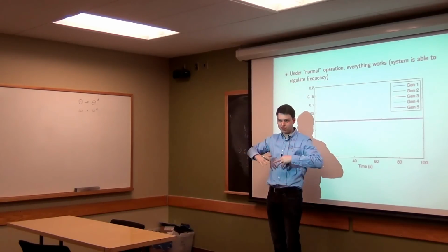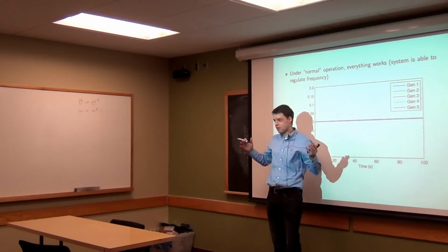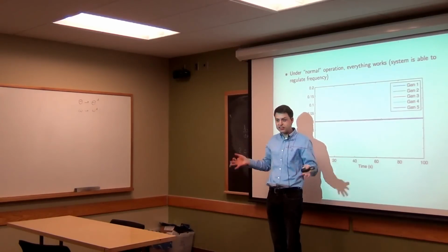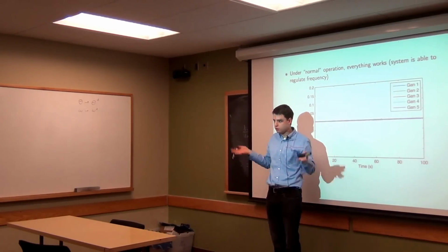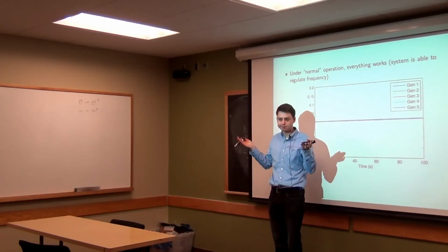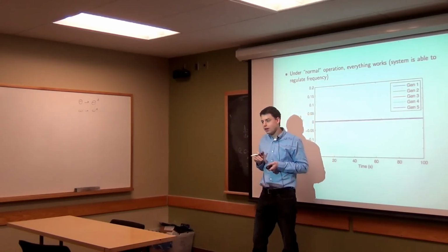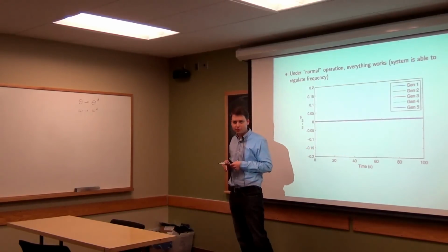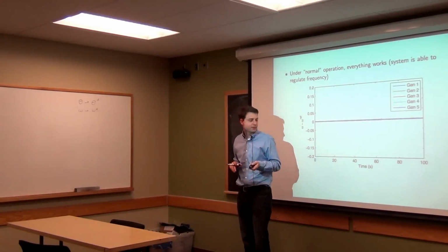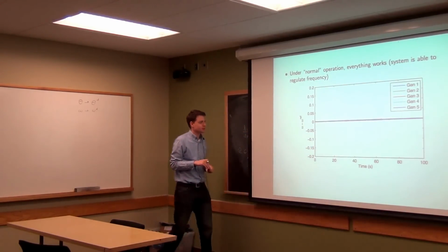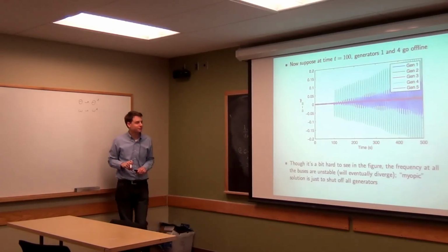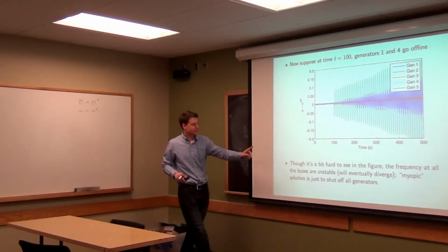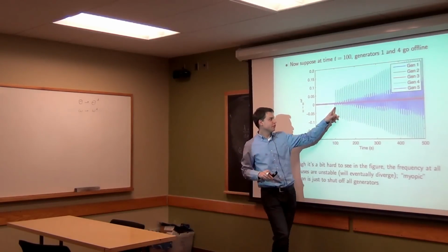Maybe the overall frequency starts falling, but the other generators that are still active will step up their power to account for their guys. Things can work out okay. And it can work out okay sometimes. But what sometimes happens is something like this. So the outage happened here at generators 1 and 4.